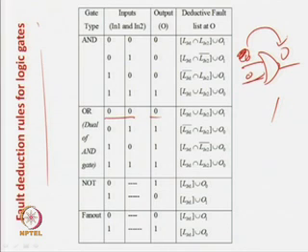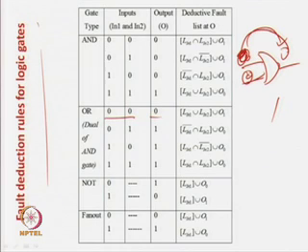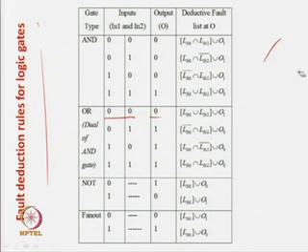In case of an AND gate, if one input is 1, then whatever happens at the other input gets propagated. And in case of an OR gate, it is just a dual. So, if both of them are 0, whatever is here propagates over here. But you know that in an OR gate, if one input is 1, then the answer is 1 and nothing gets propagated. So, just by applying the dual rules, we find that if both of them are 0, then both the lists will be propagated, that is the union, and of course, the output is a 0. So, a stuck-at-1 fault will be detected.